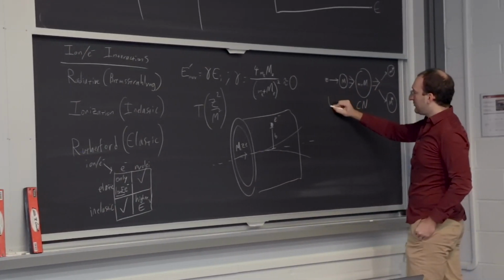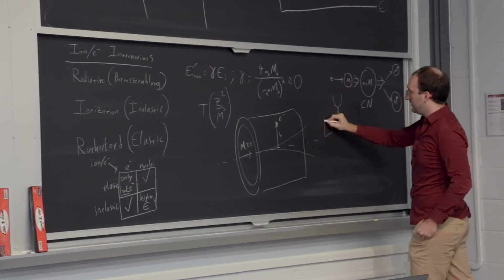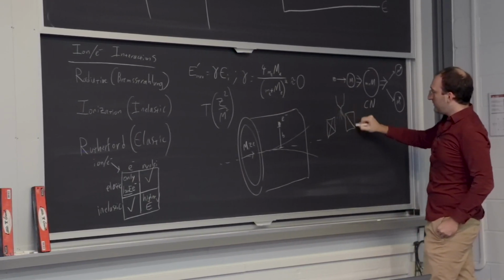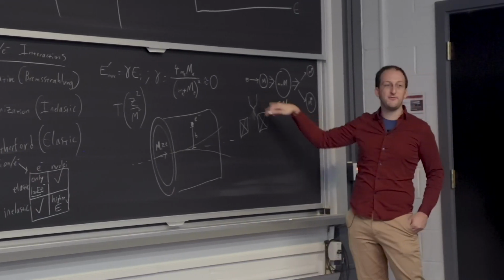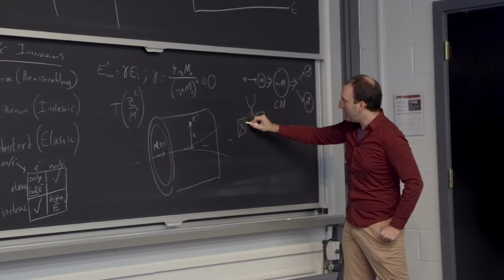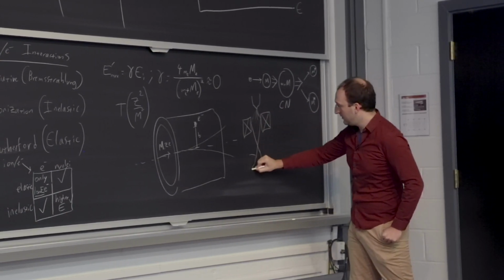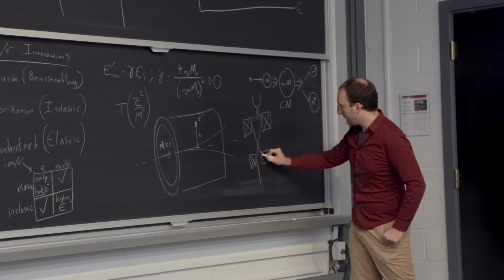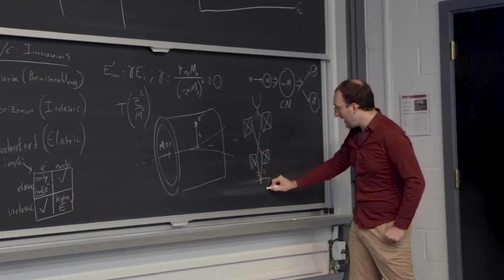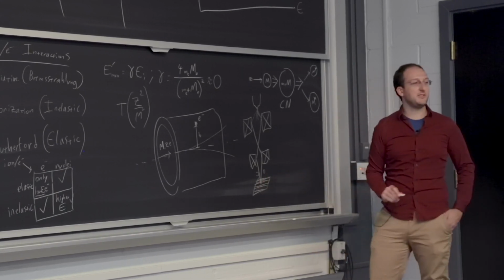So let's say you have this electron filament giving off electrons in all directions. When you see boxes with X's like this on an electron optics diagram, it usually means this is a focusing coil of some sort. That will cause the electrons to get bent and focused. There'll be another set of coils that focuses them further, and some scanning coils that actually raster, or XY scan, this beam across the surface of a material.